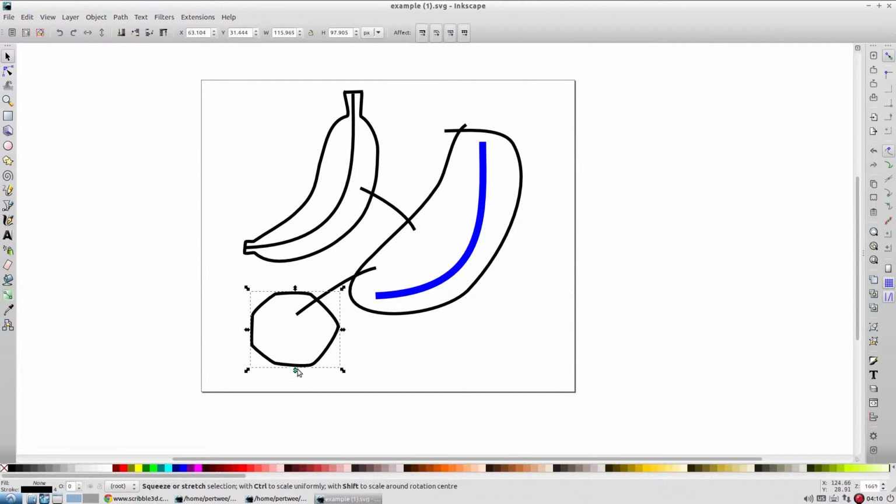This cross-sectional slice is extruded along the blue-coloured spine path. Imagine this slice to be rotated in 3D and placed at various points along the spine path. Rotate each slice so it is always perpendicular to the spine path in a 3-dimensional space.